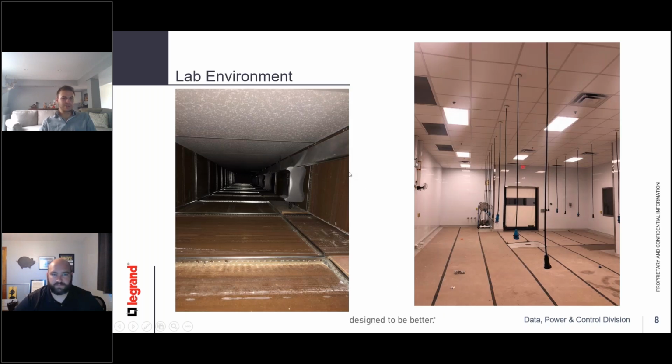We wanted to show you a couple pictures. This is one right here, which is obviously a restrictive area. This was a washdown area in a lab, where the busway is actually above these ceiling panels up here. There are regulations and codes that you have to be careful with. Obviously, it cannot be in a plenum. This is not a plenum rated area, and this was allowed by code to be up in here. But you can see it's a tight area. We're not dealing with a whole lot of space here. We're putting E90s in here, and then the busway is mounted right to here as well.